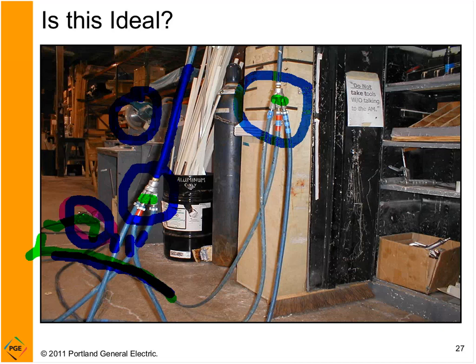Well, just like horses, forklifts drive on the ground, and they step on things. And when forklifts run over hoses, the hose loses. Eventually, you get fatigue and wear and holes and leaks in your hose. And leaks not only waste your precious air, but they also increase the pressure drop because of the velocity through the air. So there we go. Lots of interesting things here. Okay, next.